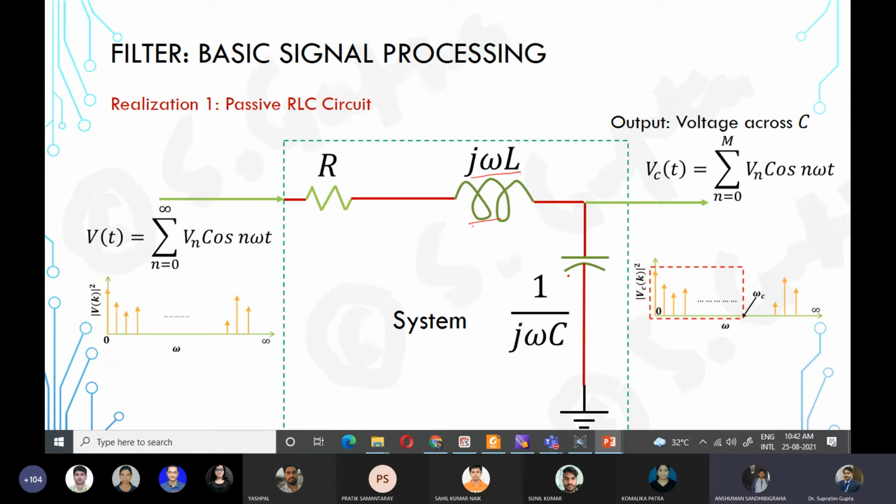Reactance and capacitance. Yes, very good. Now, what is the effect? Even if you do not understand maths in greater detail, you can understand this, the division. If I increase this omega, this value will decrease. And this value will decrease means if omega is infinity, this is a short circuit. So whatever current is flowing with the frequency omega equal to infinity will all pass through this. It will be passed to ground, right?